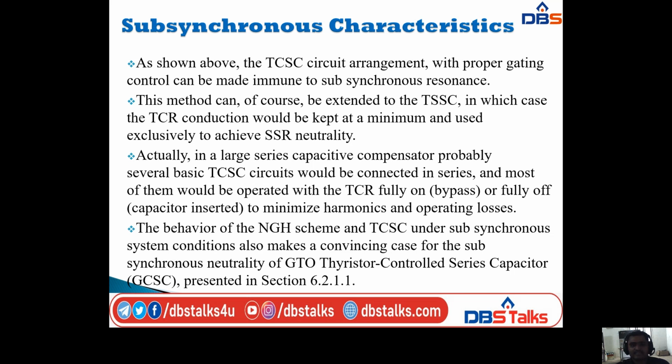Okay, and as shown above, the TCSC circuit arrangement with proper gating control can be made immune to subsynchronous resonance, that is SSR, and this mention can of course be extended to the TSSC, in which case the TCR conduction would be kept at a minimum and used exclusively to achieve SSR neutrality.